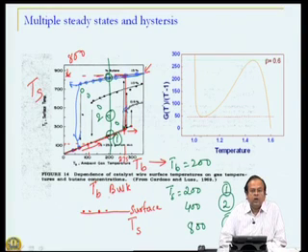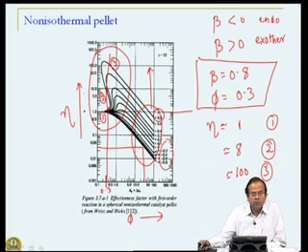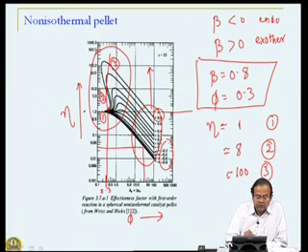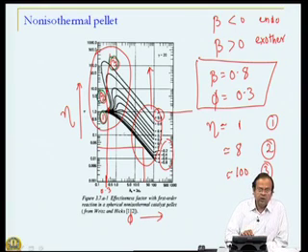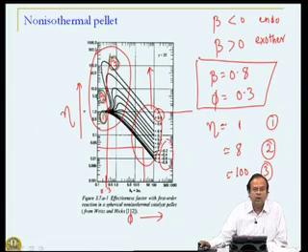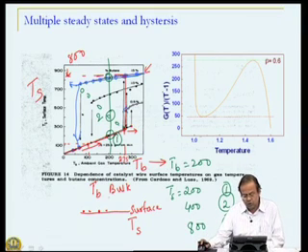So, now let us try to understand or analyze this situation. This is easy to analyze, and therefore, we will analyze this. But I want to again draw an analogy with the previous scenario, that is same conditions, 3 different solutions, 1, 2, 3. The reason for both these solutions is the same, the reaction is exothermic, only here we are looking at internal mass and energy transport limitation. We will illustrate this same idea with external mass transfer limitation, which is relatively easy to look at.